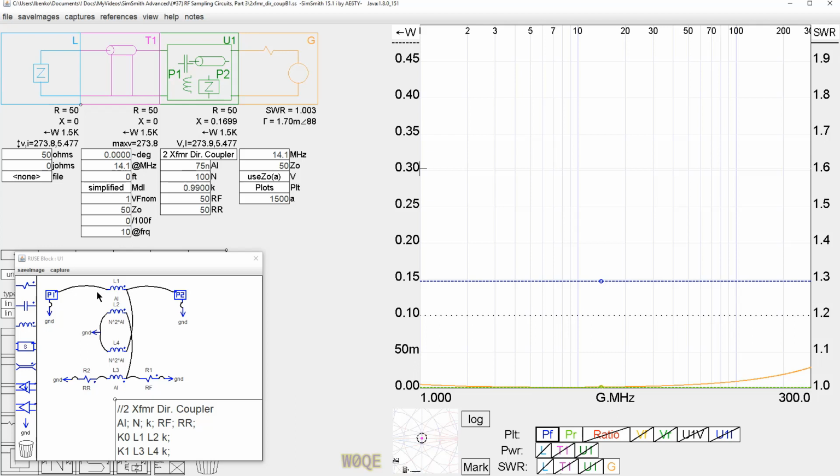analysis right now because we included them kind of ad nauseam, I guess, in the previous circuit. And if you want to analyze this circuit, you can certainly put a capacitor here to here, and here to here, and then figure out what's going on, like I did before. But bottom line is running the shield of the coax through the center turn, through this one turn right here, leaving it open on this side and connecting this side to ground gives you better performance than just running a bare wire through it. And that's what I built in my circuit too.